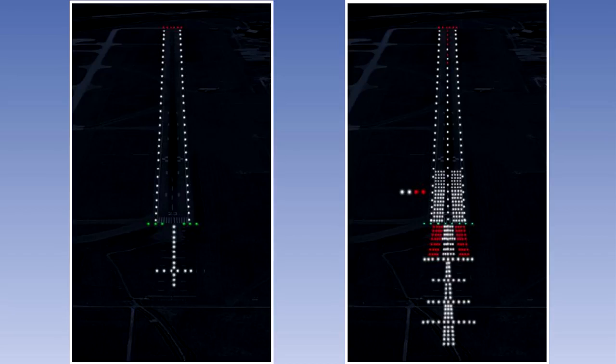The determination of the visual criteria for landing can be met by the visual acquisition of the approach light system, and the design must cater for the most stringent decision heights and minimum descent heights. Approach lighting systems have developed more or less in line with the advancement in technology associated with instrument approach accuracy and demands. But all layouts, no matter what their design, must comply with the ICAO metric specification. Any ILS or MLS azimuth antenna that protrudes through the plane of the lights must be treated as an obstacle and marked and lit accordingly.